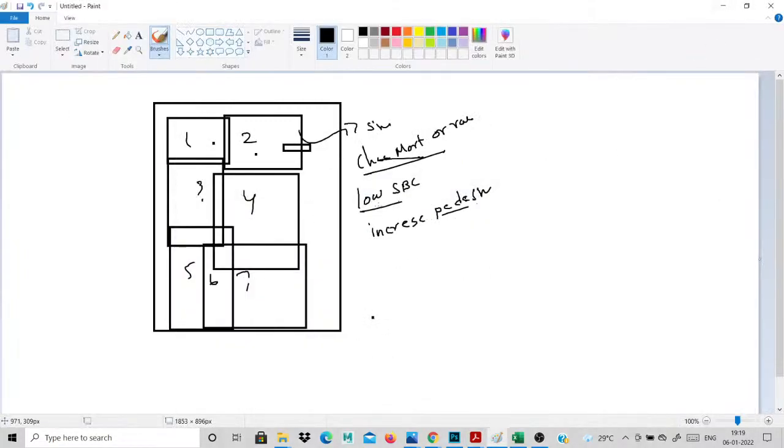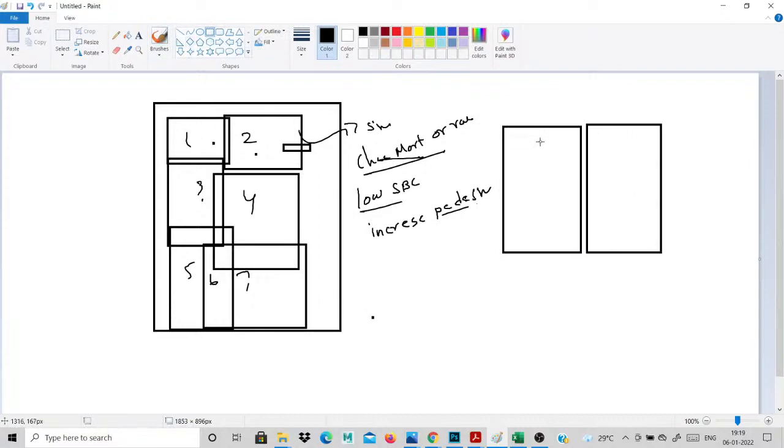The next point: near the boundary lines, combined footing or strap footing will be provided. This is our area and this is our boundary. This is block A and this is block B. I put a column for combined block A and block B, so two columns are nearby and the pedestals will be large and clash.